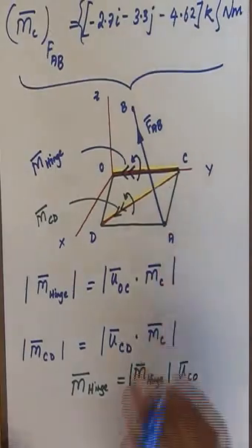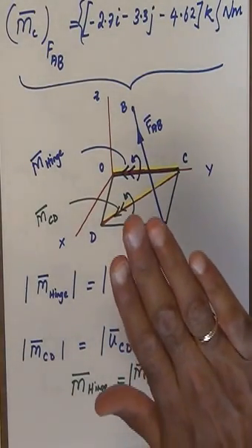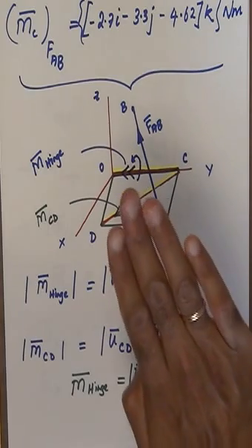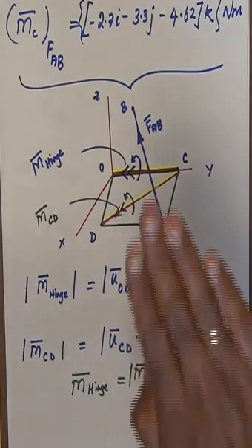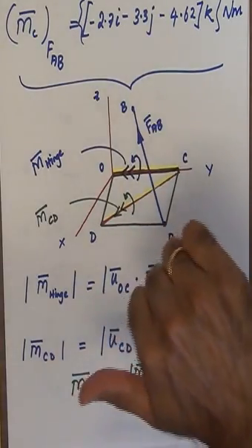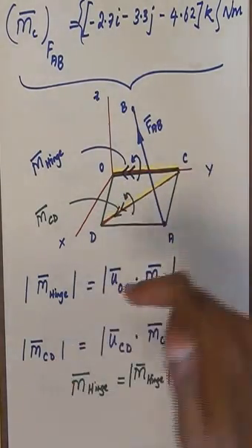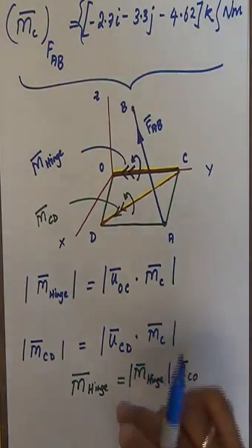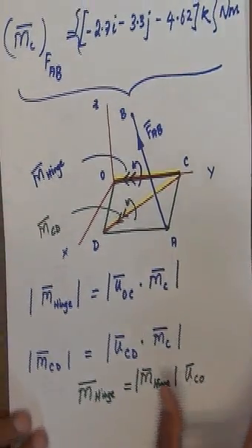This is because of the right hand rule applied for the moments: line of action of the force coincident to the fingers of the right hand aligned in that direction, my palm faces the line or the axis of interest. I curl my fingers, look at the direction of my thumb, it's directed from point C to point D. So that's going to be the direction of the moment, and the sense of the moment is curling about that particular line. So I need UCD.